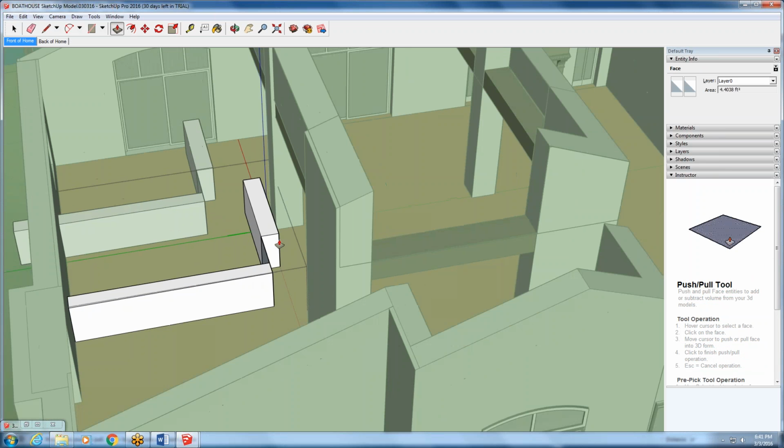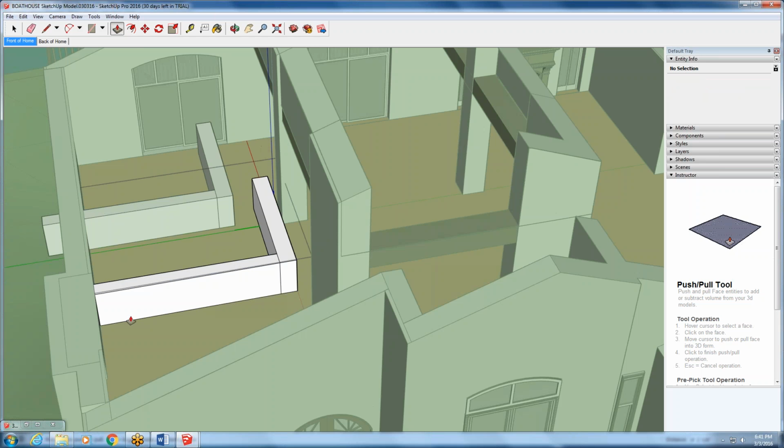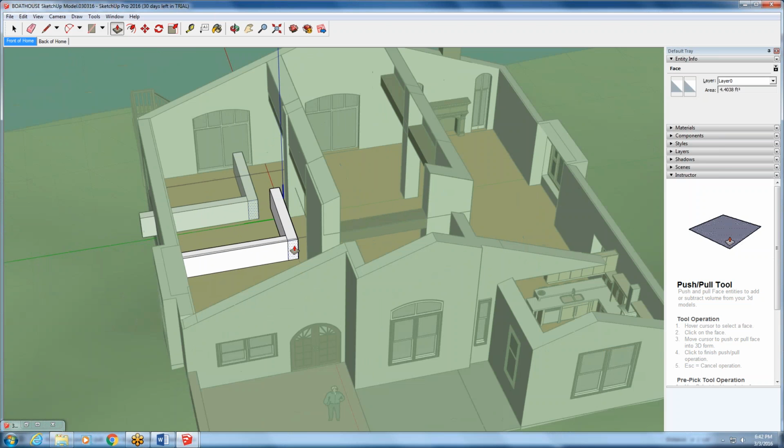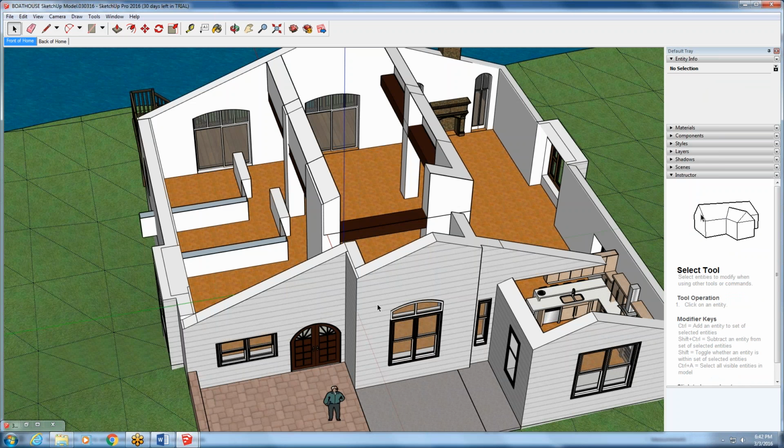So the majority of the work that you'll be doing drawing walls, I just want you to make a group. I don't want it to be modifying other things within your drawing, and really you don't need copies. But that's what a component does. A component is a group that has this property to it of being able to copy in the different locations that you've pulled it into your drawing. Okay? So I can double click to get out and hit escape.